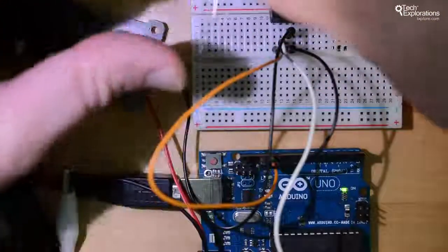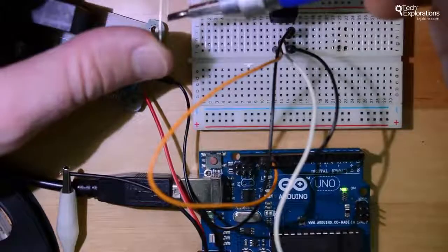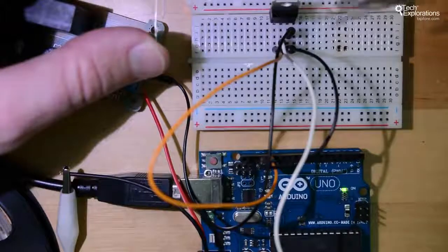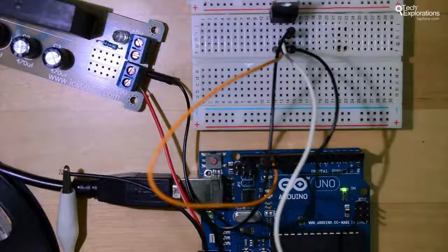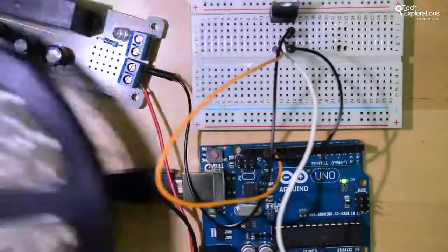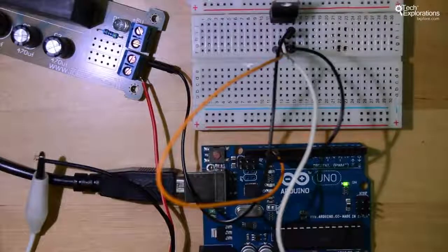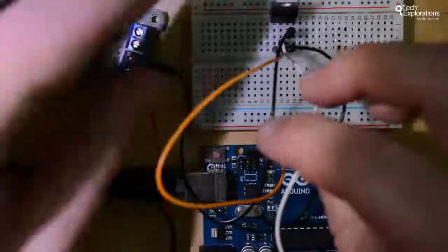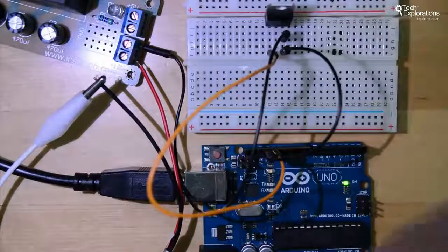One thing to remember is that unlike the 5mm LED, you can't just look at it and figure out which pin is short and which pin is long. So you don't really know which one is the cathode and which one is the anode. It just comes like this, and you've got two wires sticking out. Of course they're colored, but sometimes that doesn't mean much. So to figure that out, what you can do is plug your LED wires directly to your power supply, and if it lights up, then you know which one is the anode.